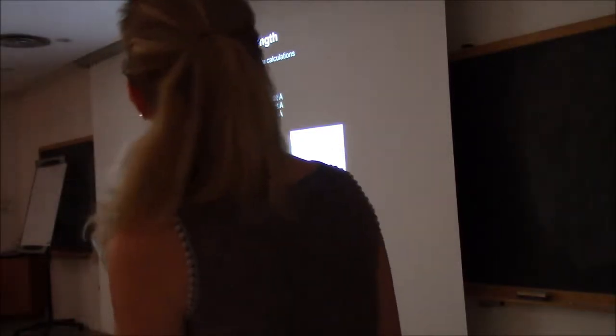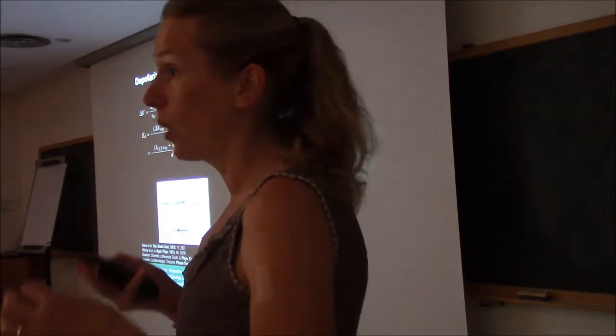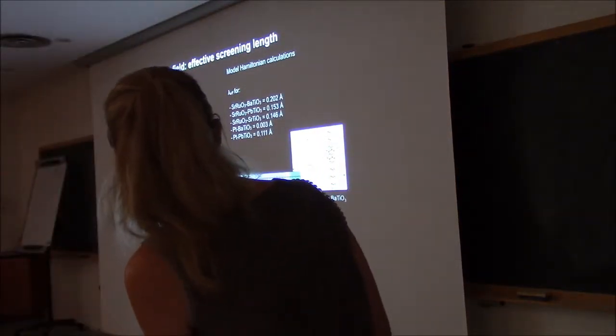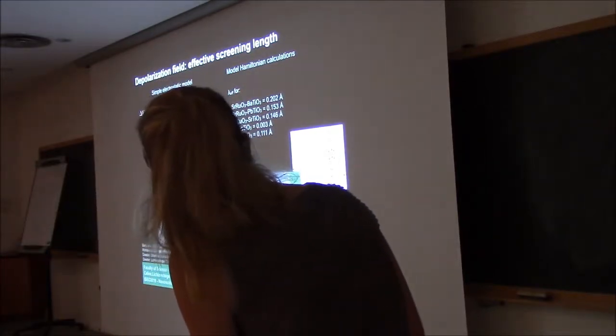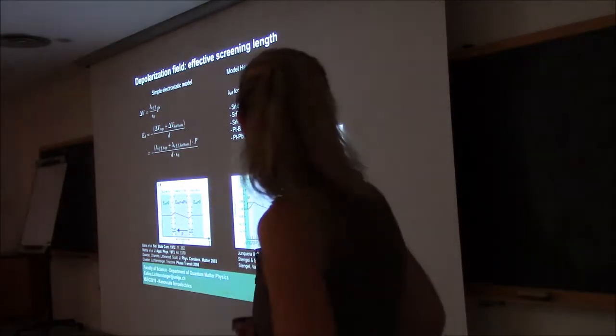And so the idea, using a model Hamiltonian calculation, is to calculate this potential drop at the interface between different materials. And so here you see again this potential drop. So it's not exactly linear. Again, this is a simplification, but you see that you have a voltage drop that induces a voltage and a field inside the ferroelectric layer.